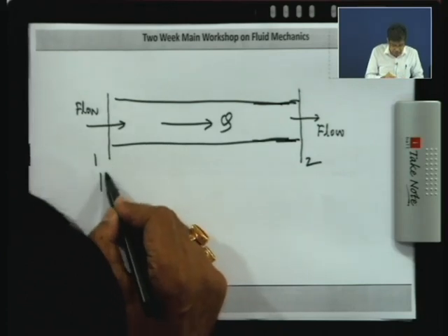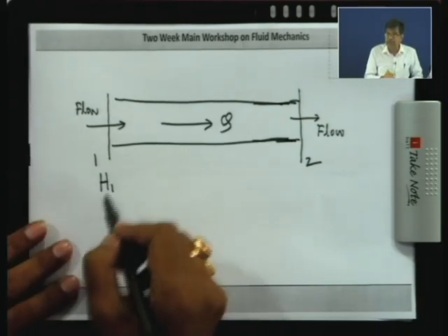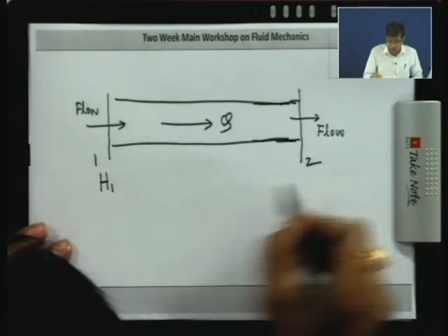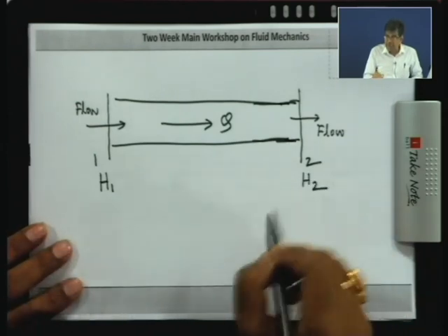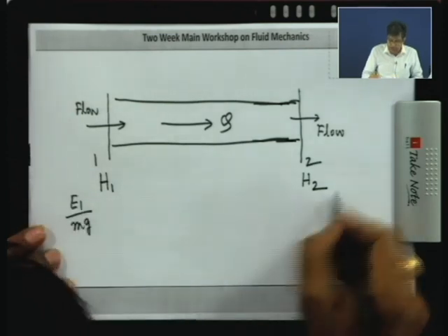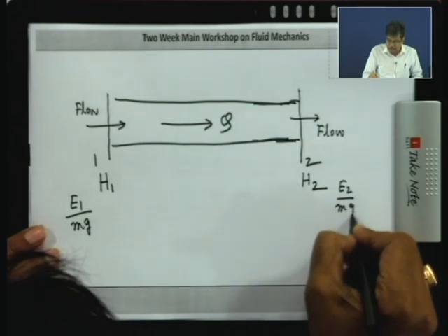So, here we take all the mechanical energy: kinetic energy, the pressure energy which comes from the concept of flow work, and the potential energy. So, therefore, here is the loss term. Otherwise in conservation of energy, loss should not be there because energy is neither lost nor created; this is the conservation of mechanical energy. Now, if we define the energy per unit weight as head, which is a terminology used in hydraulic engineering and by engineers in practice, and if this is the total energy per unit weight as H2, the dimension is meter.